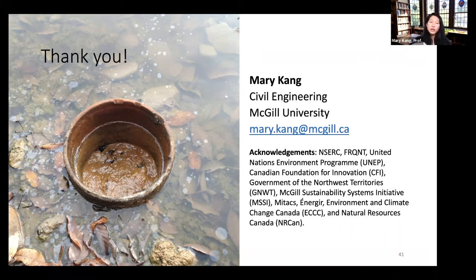And then we also walk around to find hotspots. So we'll walk around with a sensor to find hotspots. We'll drive around with sensors as well. And we also have some drones to fly around to get different screening. So this is a multi-scale measurement system along with a good understanding of the infrastructure data. So you have to know where the natural gas distribution lines are. You have to know where the different infrastructure is to estimate how much is coming from them. And then we do some spatial temporal analysis.